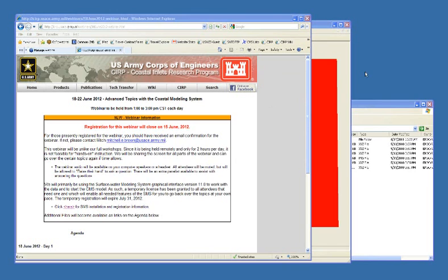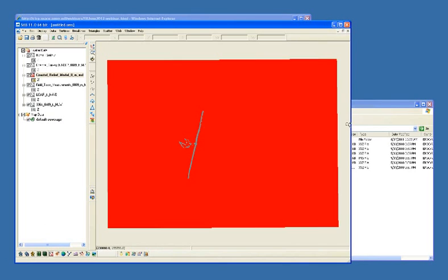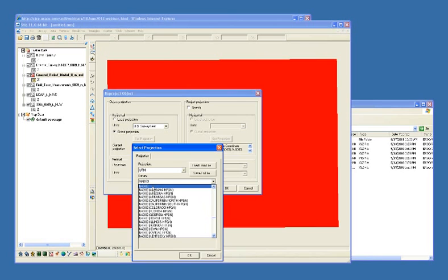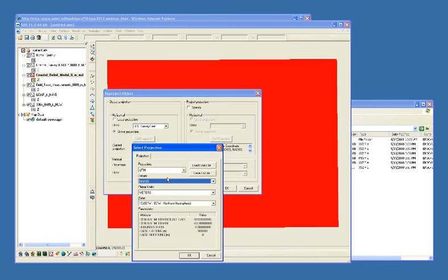For a horizontal projection, you may have a choice between, let me go to the screen here. Sometimes you may have some data that came in NAD 83, or NAD 27. That's the only datum that you might have to switch between for the horizontal. For vertical, that's a totally different story, and we're going to discuss that tomorrow. And hopefully that answered that question, Julia.